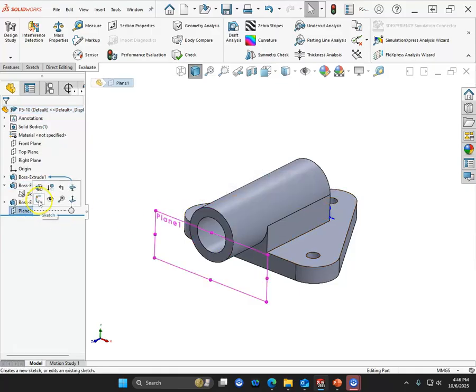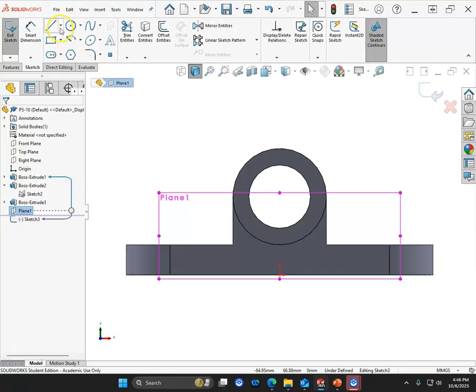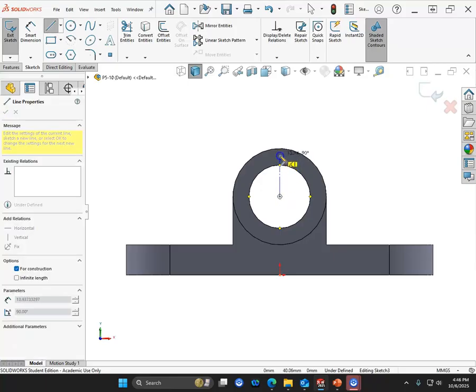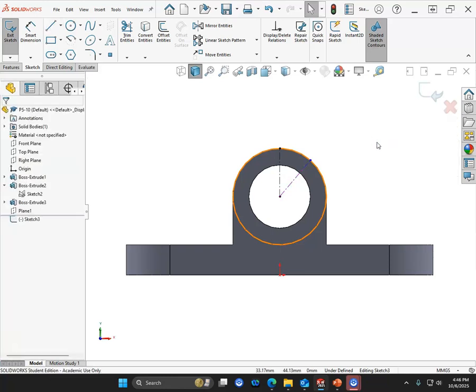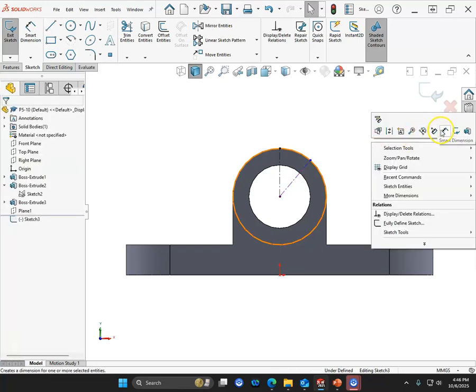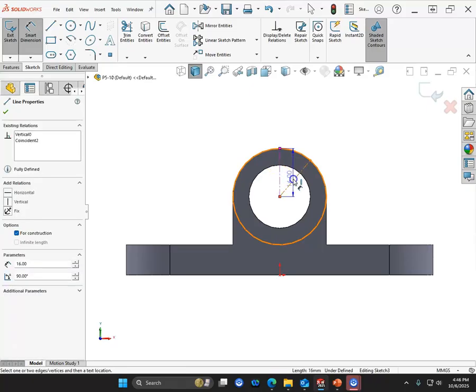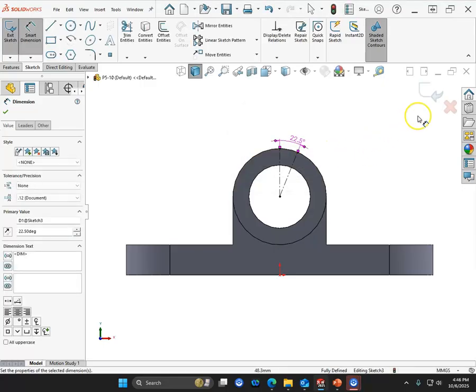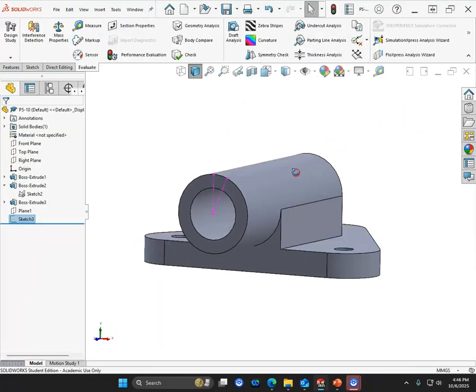Well, since I created the plane, I don't necessarily need the plane, but I can come back and use that sketch. And if for some reason it needed to be off at an angle, then we would be able to control that angle with the sketch as a clocking mechanism. So let's go half of 45, 22.5 degrees.